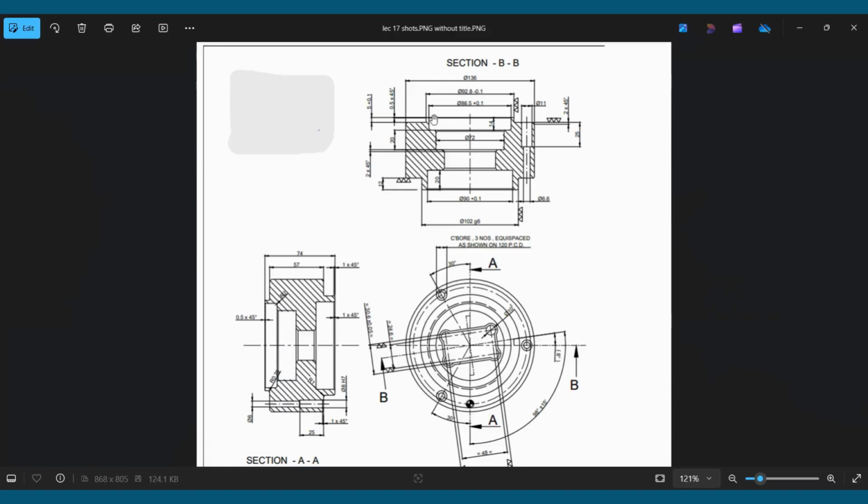Next we are going to go for this internal feature using revolve only. So first these two profiles of diameter 86.5 and 72 are going to be made. Then this gap, that is this rectangular cutout, we are not going to make in this sketch here. Lastly we are going to make this 90 mm diameter cutout profile, and then we are going to go for revolve cut feature.